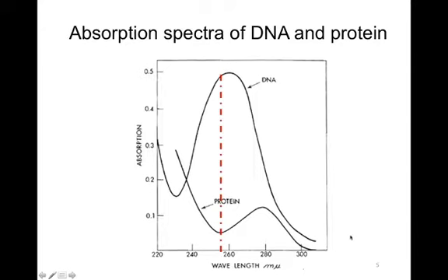What is really interesting to see, and the reason why low pressure UV disinfection works, is that here at 254 nanometers, where the red line is, that coincides almost perfectly with the absorption maximum of DNA. So the DNA absorbs light efficiently at that wavelength. You can see that proteins don't absorb light that efficiently, but they still do absorb photons of that wavelength, and so it is still possible to get damage.